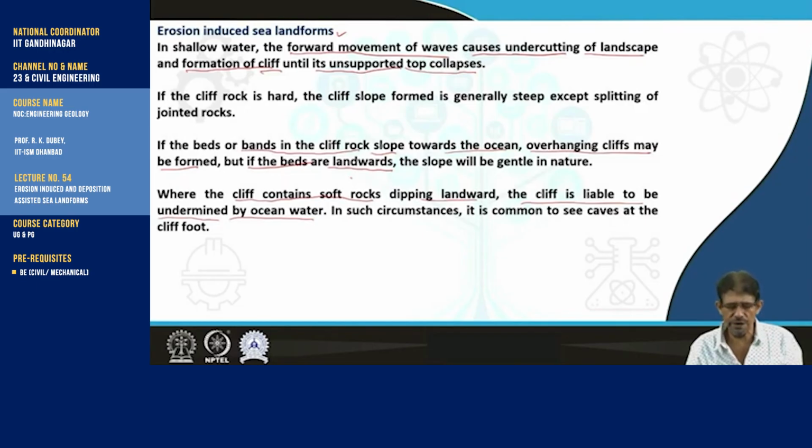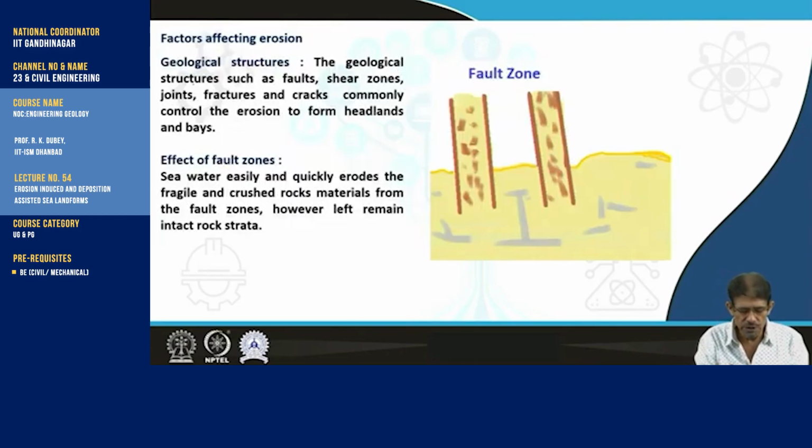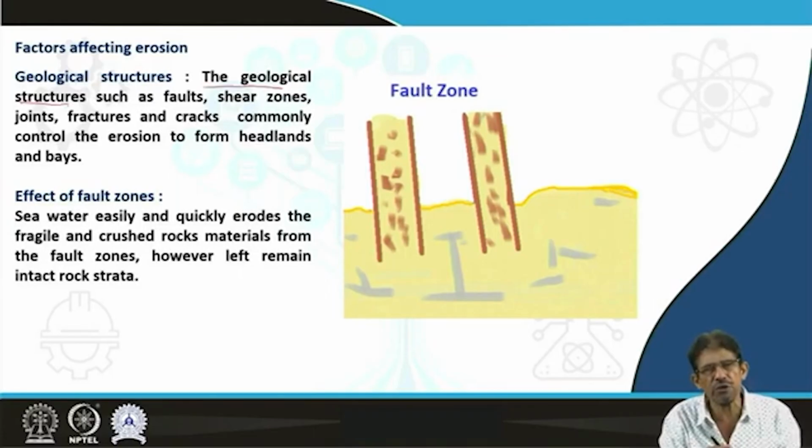stacks, etc. Among the factors affecting the erosional process, we can see varieties of geological structures such as faults, shear zones, joints, bedding planes, weathering pockets, and many features representing discontinuities, which influence the erosional effect as an inherent parameter. On the other hand, the energy present in waves, along with the characteristics of sea waves, controls the erosional activity as an extrinsic parameter.